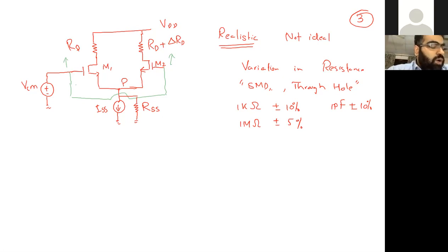So first of all, there is asymmetry. We know that. Now we need to see whether the current is going to be the same or not. That's the main important question for us. As we know, the current is going to be governed by M1 and M2. Since they are in saturation, there will be ID1 here and ID2 here. In the normal differential pair, we say that if the same voltage is applied, with the same width and length, ID1 ideally should be equal to ID2.